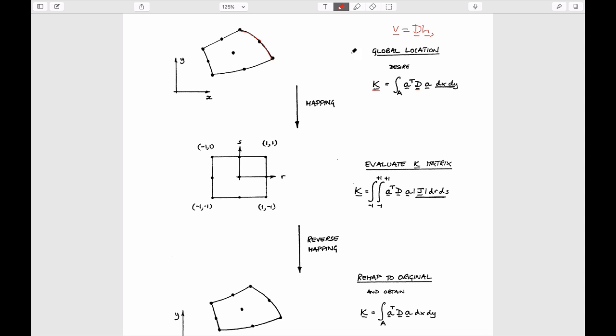And the A matrix is what? It's something that links gradients of head to nodal values of head. So these are the basic forms of these two matrices that we need to be able to populate this particular relationship here. If I do this, A transpose is the transposed version of A. And so these inhabit an integral.